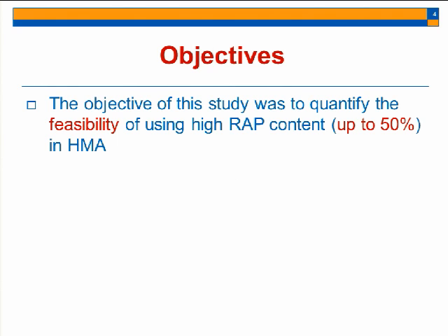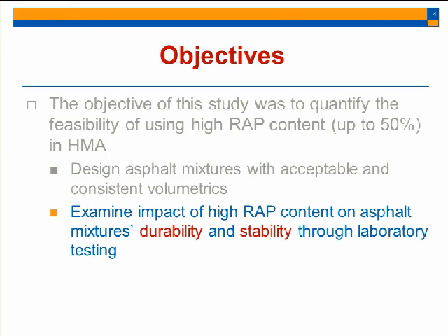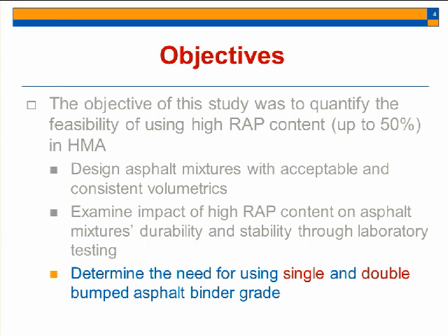The objective of the study was to quantify the feasibility of using high RAP content, by high I mean up to 50% in HMA. And for that, we needed to see if we can actually design such high RAP mixtures with acceptable and consistent volumetrics or not. Also, we wanted to examine the impact of high RAP on laboratory performance, like durability and stability. We were also interested to see the effect of single and double bumping on these RAP mixtures.